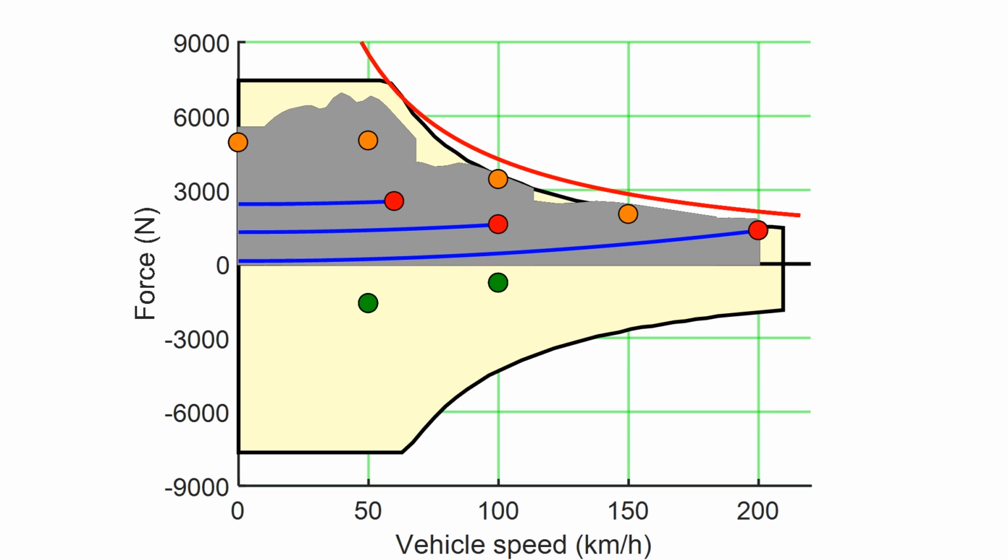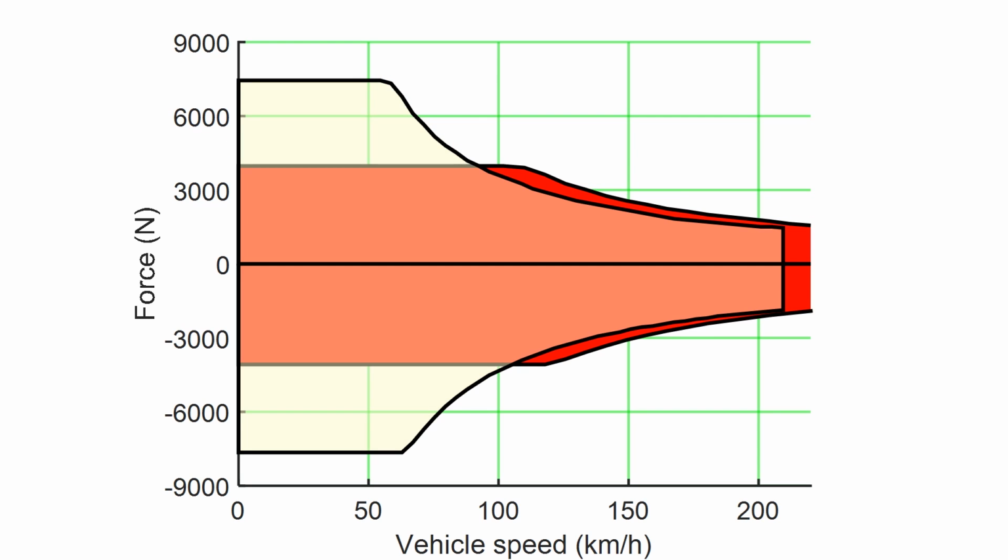Despite these advantages, we see that the electric powertrain struggles with the high-speed acceleration requirements. If the high-speed performance can be increased, it would be possible to reduce the size of the electric machines, since it has no problem of meeting the low-speed requirements. A solution to that can be to add one more gear.